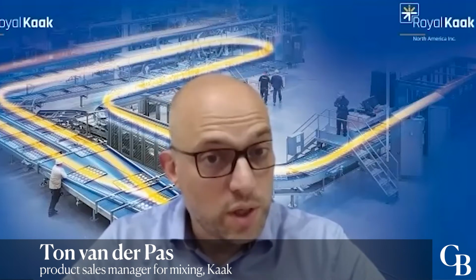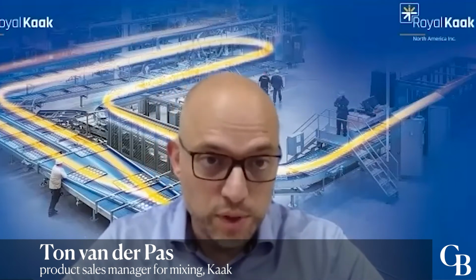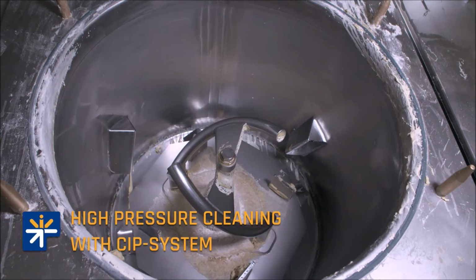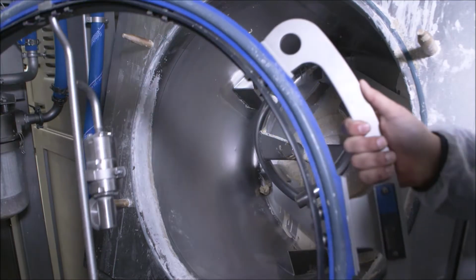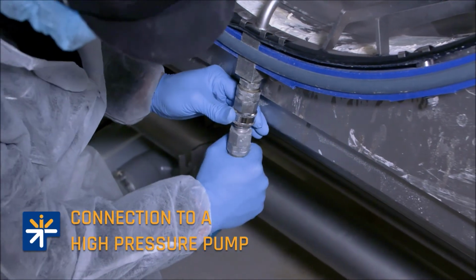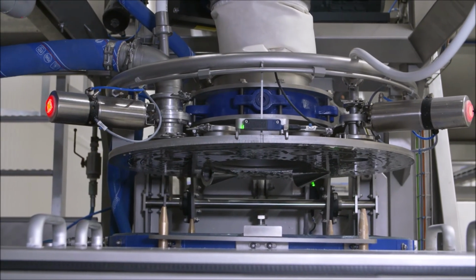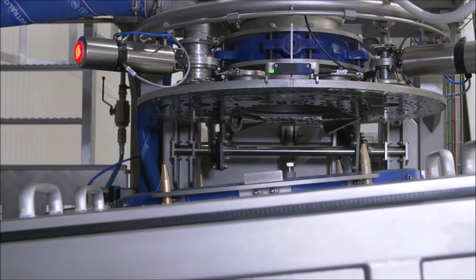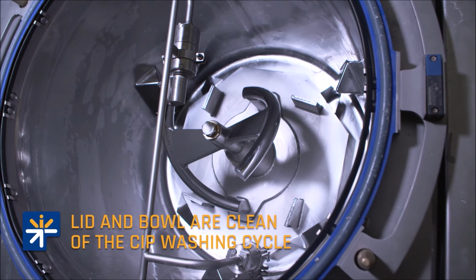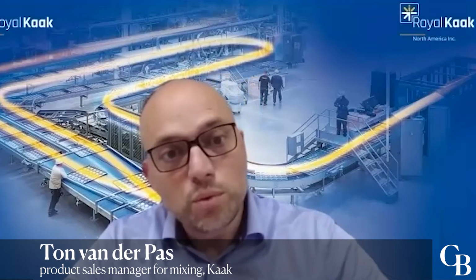So the mixer itself is washed down. That means also that there is no dust going into the machine, but also not going out of the machine. Besides that, we have a patented CIP system for the mixing bowl itself. We have a kind of special ring which we put on the mixer bowl. And then we run a sanitation program like your dishwasher at home. It has several stages where you have a deep cleaning, where you have a soaking stage, so you can program it yourself. So you don't need to climb into the mixer. Hand scraping, so it also saves a lot of manpower. But also the mixer is completely clean, not only on the bottom, but also in the lid.